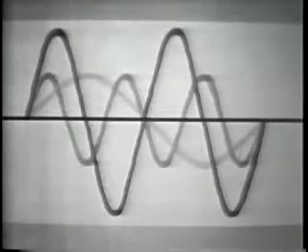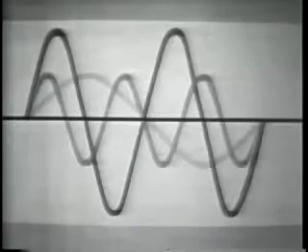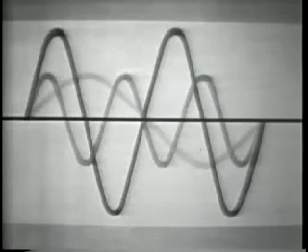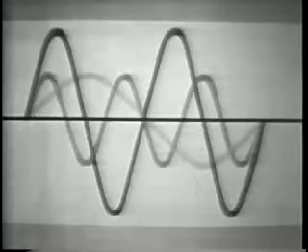It shows the instantaneous summation of these voltages. When all three are in phase, the resultant is large. When the sidebands are in phase with each other and out of phase with the carrier, the resultant is small. Thus you see what only appears to be the carrier varying in amplitude. But back to the composite waveform.